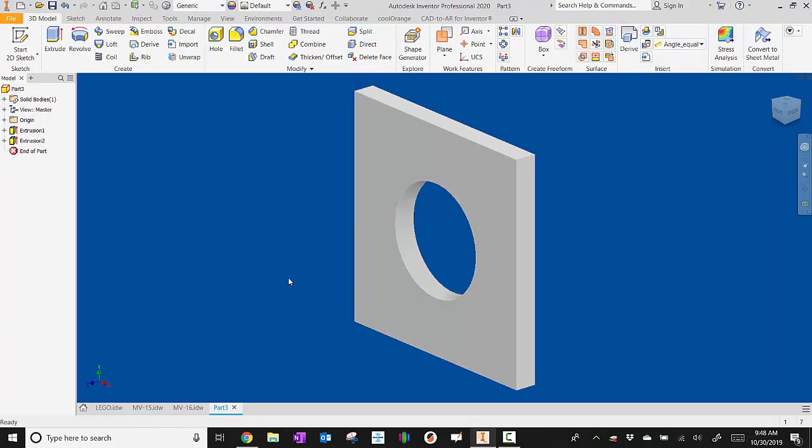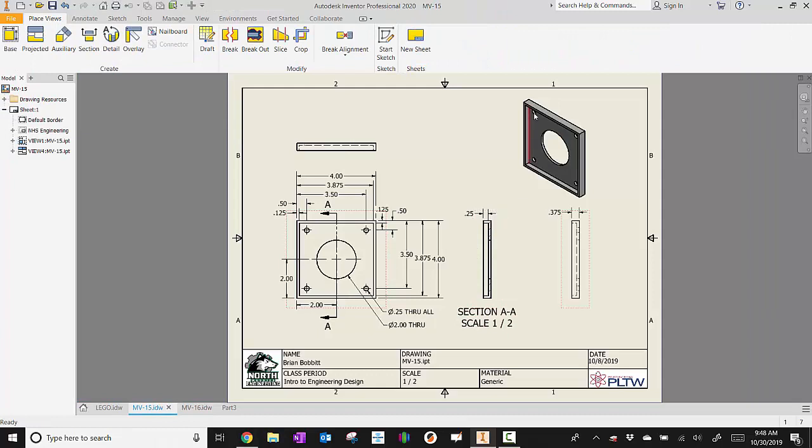Okay. Now the next thing, or it depends on how I want to look at it, but I know that there are 4 circles. So there's 4 holes in the corners. And I know it's depressed in there a little bit. So if I look, looks like from here to here, so this little lip around there, it looks like to be 0.125. It also looks like from the top to this lip here is also 0.125. So I'm going to make the assumption that it's that way all the way around.